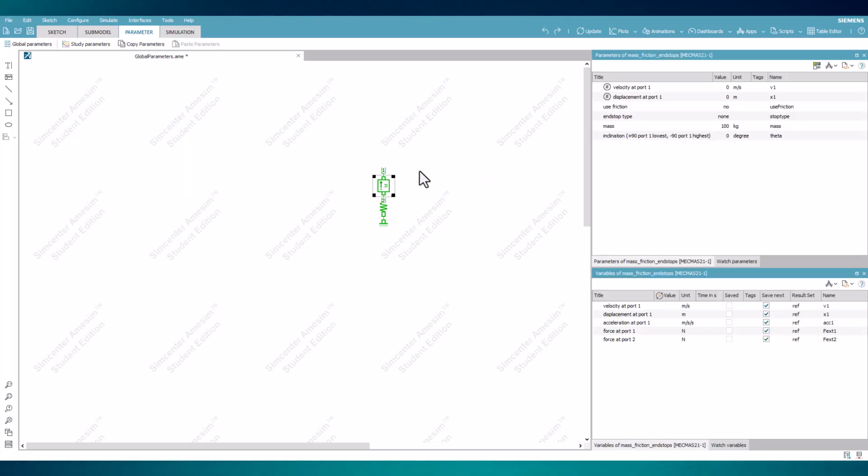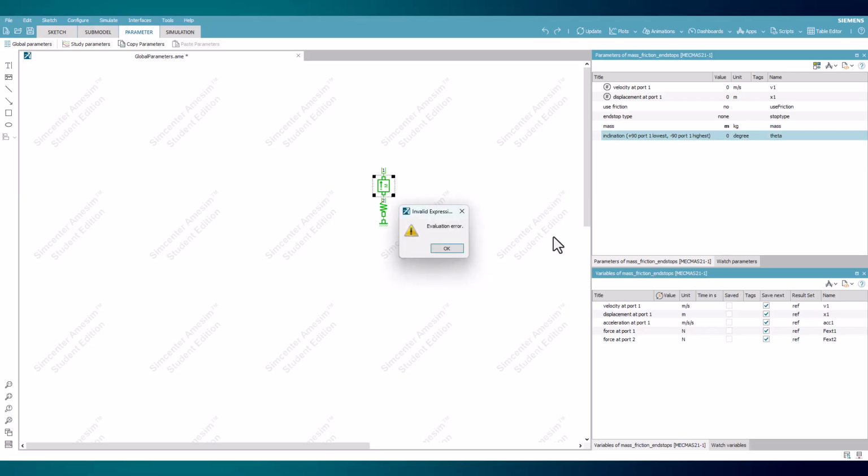When typing in the title of the parameter, as if it were a value, a box will appear suggesting the title. Once complete, the typed in value will be black within the parameter window if acceptable. If the global parameter value is not acceptable, like if there is a typo, the text will appear as red and an error message will be shown.